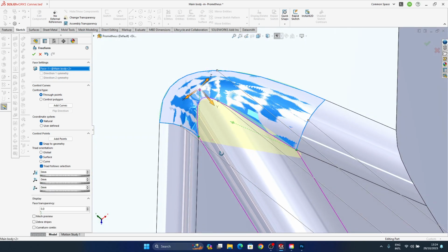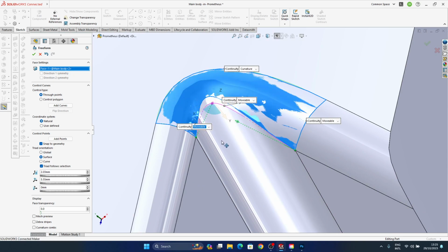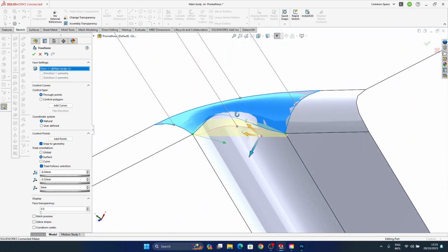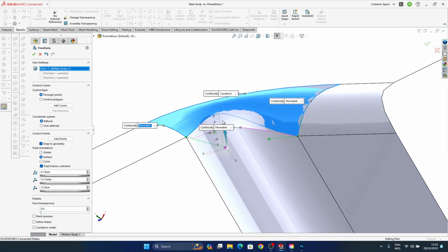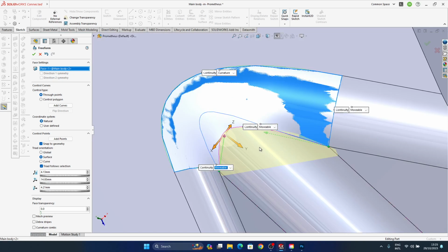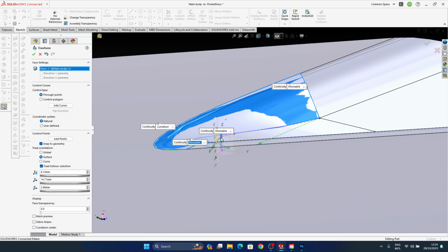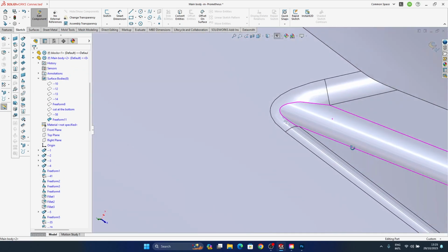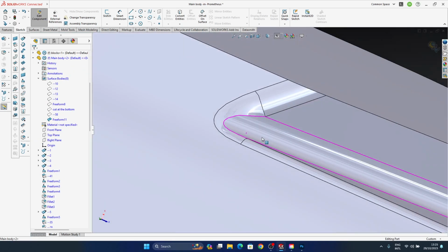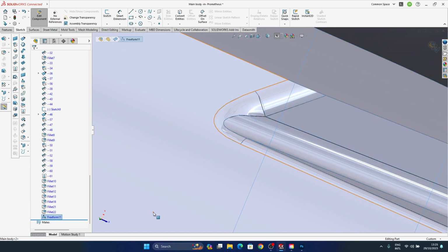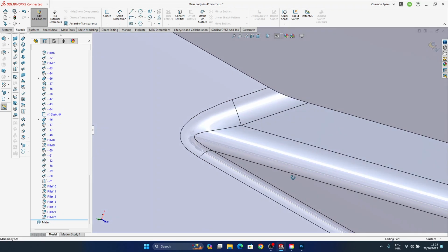I'm curious if SolidWorks would actually update the surface with whatever I am choosing to do in here, relaxing these fillets around, if it's going to still close the body. So if I'm committing to it right now, let's see if SolidWorks does it. Yes, it does. But of course, it will get me something weird and extending this surface. So definitely I don't want that. Still useful for different stuff.